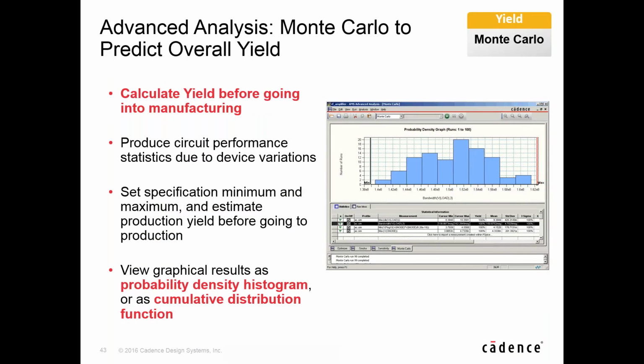And then finally, we have yield analysis, which can introduce cost savings in your design. So you have your circuit, and again, you have your measurements, which are shown here in the screenshot: max dB of V load, bandwidth of V load. You have discrete devices in your design, and when you manufacture a couple thousand of these things, you're not always going to get the exact combination of the devices that you've placed in your schematic. Their values and other parameters are going to vary as they're picked and placed in the design. So Monte Carlo yield analysis is going to randomly vary those things and show you what your yield is going to be with the random combination of those devices.